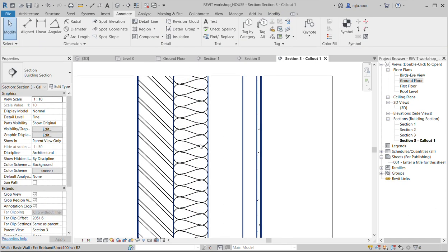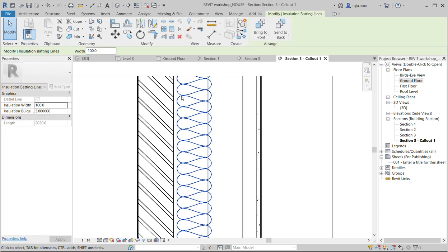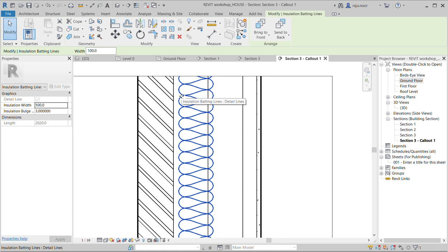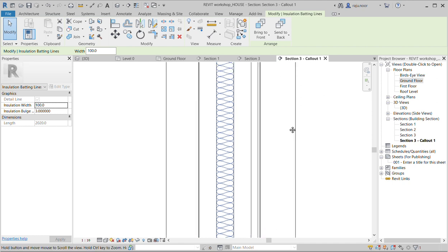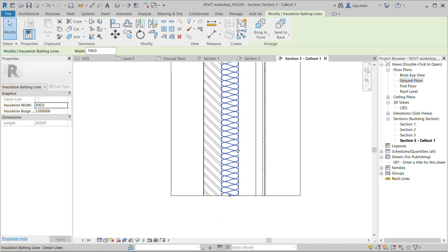You can also manually move it by hovering over the wall detail, using the Tab button to find your actual material. Then you can use your arrow buttons to nudge it into position if you want finer detail on the location of where the component should be.